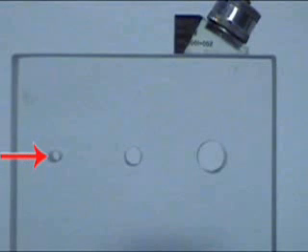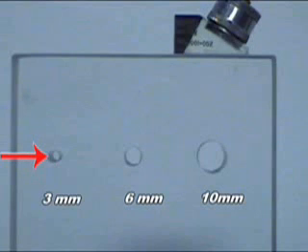The glass block was fabricated with 3 holes drilled in it. These are nominally 10 mm, 6 mm, and 3 mm diameter. An internally spherically focused probe was selected to minimize the off-axis effects. The probe used has a 12.5 mm diameter with a nominal frequency of 7.5 MHz. This compression mode element has a 150 mm radius of curvature.